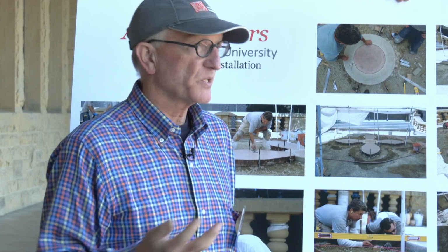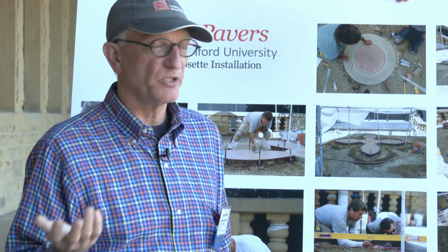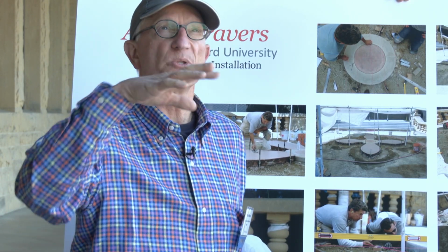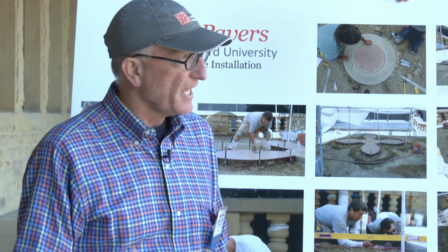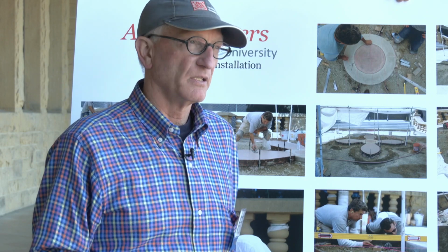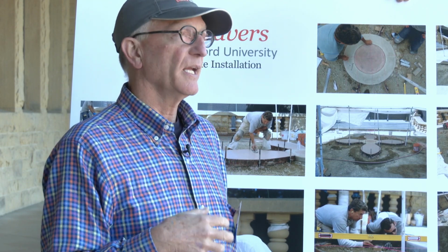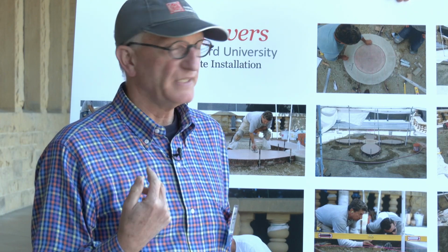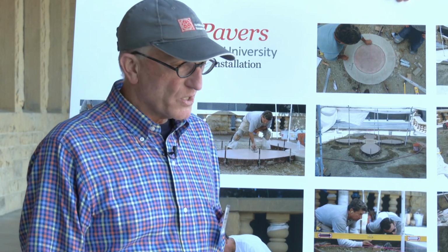And most architects and conservators and engineers that work with buildings, you look at a building and you see an orangish-brownish stain, and you say, it's reinforcing bar that's corroding inside. And so that eventually is going to disrupt the masonry, and it's going to be damaging to the building.